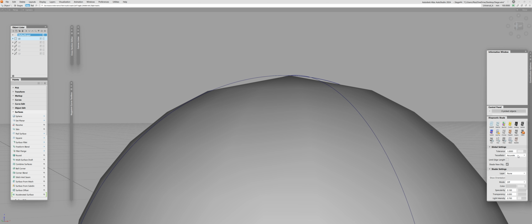Well, the first question you may ask is why? Second, how? And third, what about it? Is it a big deal? Well, why is quite simple. NURBS geometry is too complex to visualize. We actually do not have a good solution to visualize something infinitely accurate on a computer. And extremely smart people found an elegant solution to this problem decades ago: discretize NURBS geometry by converting it to a mesh. It is a simple process in terms of computation, so it happens in real time.